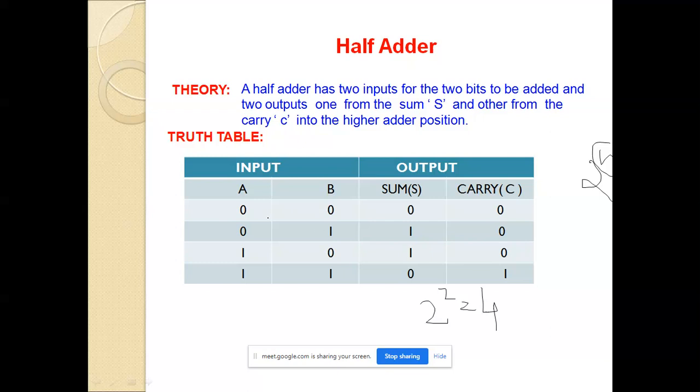What addition do we have to do? The first question, the answer should be, sir, binary addition. So now let us try to understand in the binary addition form. 0 plus 0 is 0 and the carry is also 0. Similarly 0 plus 1 is, in the sum we get 1 and the carry is 0. 1 plus 0, same, 1 and 0. And this is the peculiar thing that we must remember, that when we add 1 plus 1, we will get